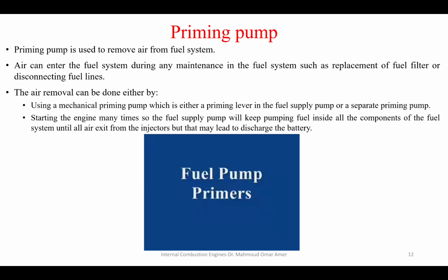Or it can be done by starting the engine many times. When you try to start the engine, what happens? The supply pump will provide fuel, and the high pressure pump will work with the engine. So they will both supply fuel from the tank throughout the system. When the engine is being cranked, all air will flow with the fuel and will exit from the injectors into the engine, the cylinder.